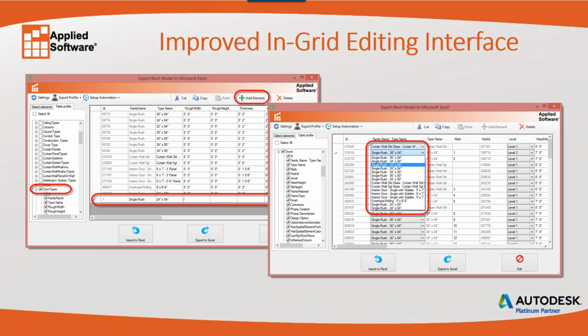When you're in the import or the export dialog box, you actually don't have to export to Excel to do editing. You can edit in the grid view here of the export dialog box, and we can add elements, we can sort on any column. We've also improved the interface to where, for example, in this graphic here, we've got a door that we've selected, we want to change it to